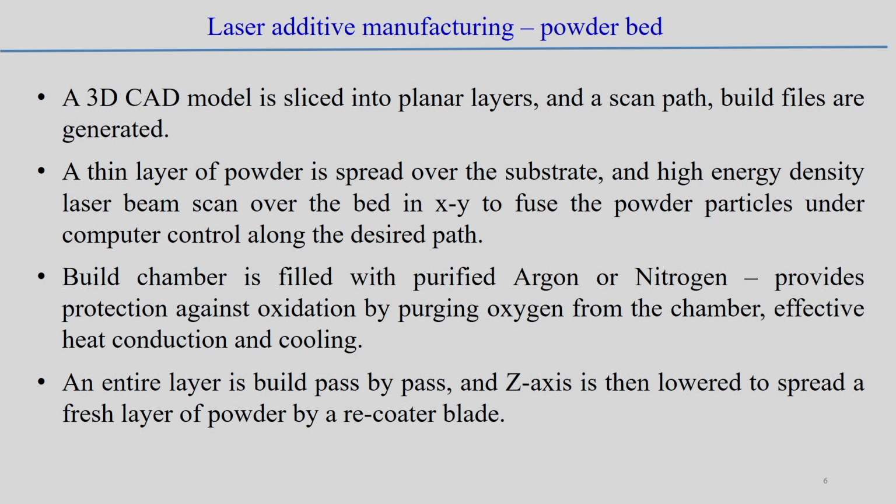Here, in detail, the powder bed based technology. You have already discussed powder based technology. It starts with the 3D CAD model, then the path is decided, and then the build strategy; everything is pre-decided. Then we follow layer by layer deposition using the XY table for movement in the XY direction, and once that particular layer thickness is done in one plane, we move the Z axis. Looking into the predefined strategy, we follow the same strategy for the next layer.